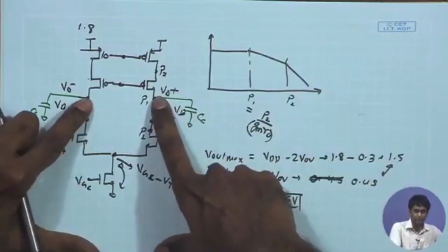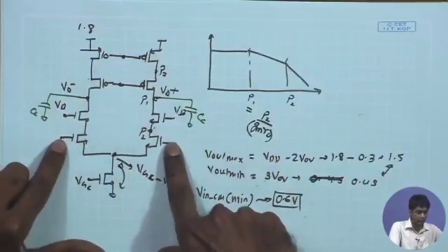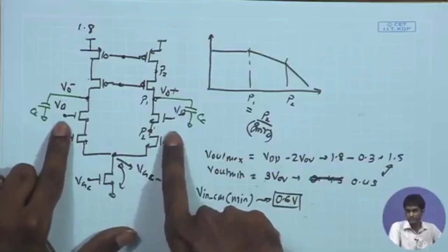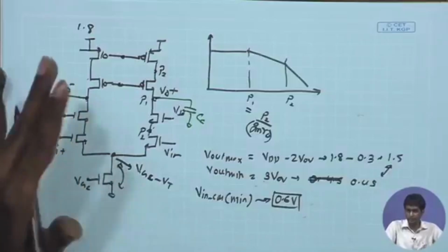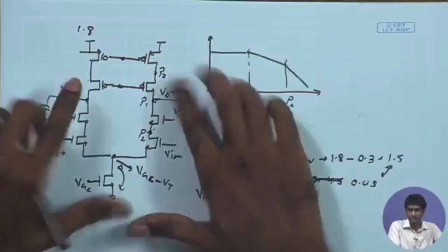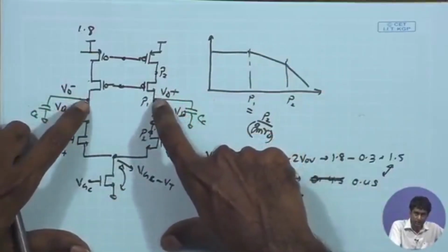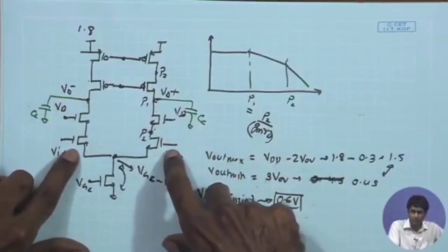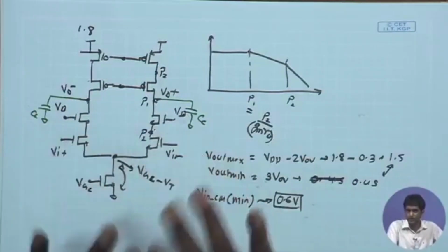The desired output DC point is 1 volt in order to allow that maximum swing, and I am going to apply that over here through that large resistor, and that is much higher than what I want for the best swing at the output. So it is not going to serve the purpose of having the best possible swing, because I cannot apply the relatively higher output DC common mode level over here for biasing the input DC common mode for my input pair. Therefore, this may not be a very good scheme.